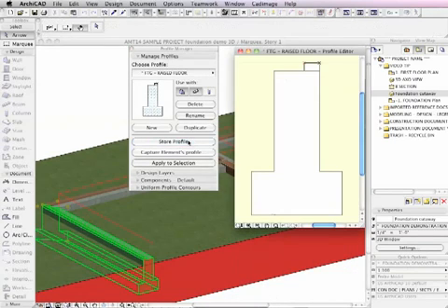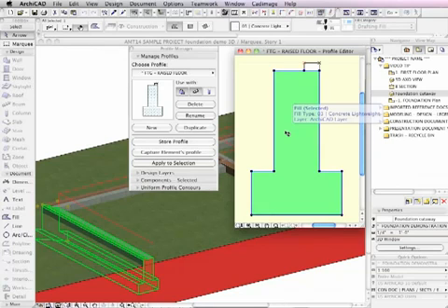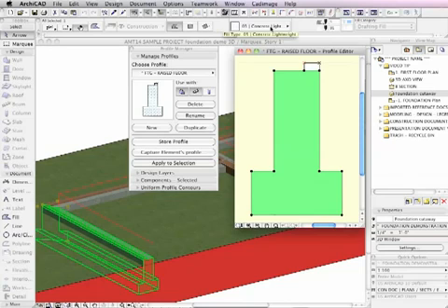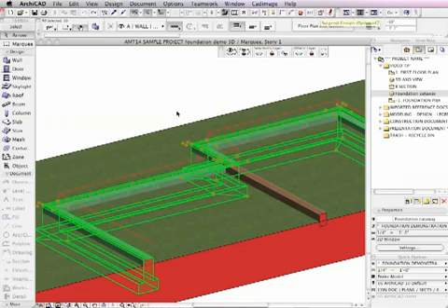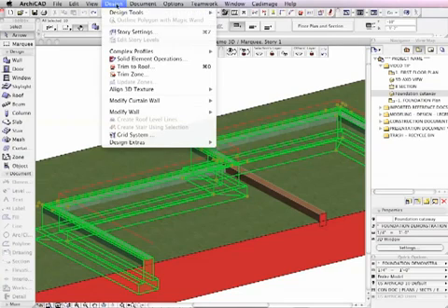I'll edit it and show you that here is one fill that actually is representing concrete, and another one that's representing the wood. Now, this element is actually part of a group, so if I turn groups back on, you'll see all of the stem walls were drawn at the same time and grouped together, and I can use them to carve out the space into the terrain.